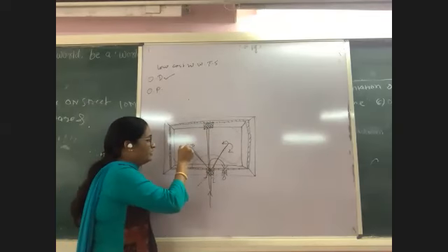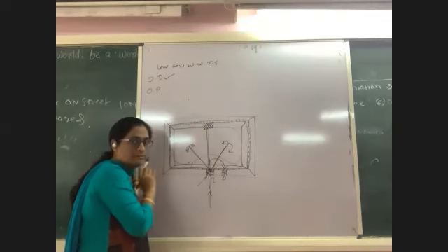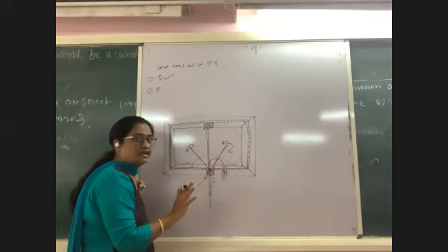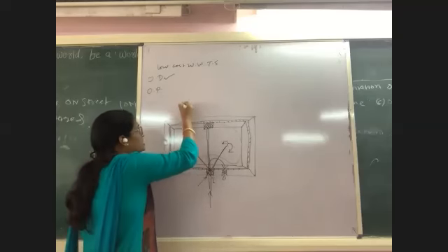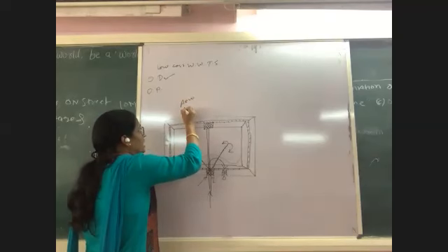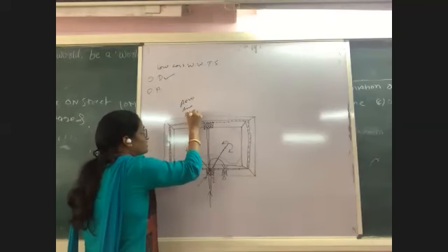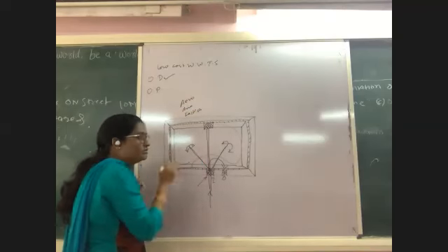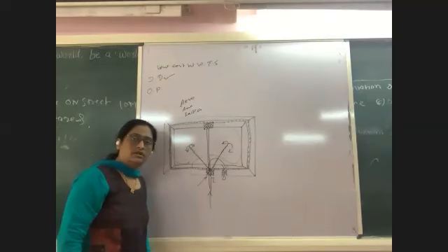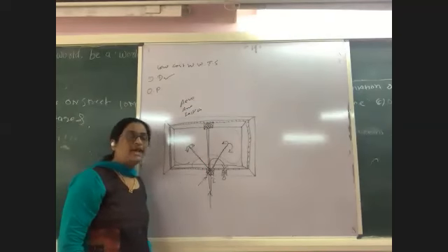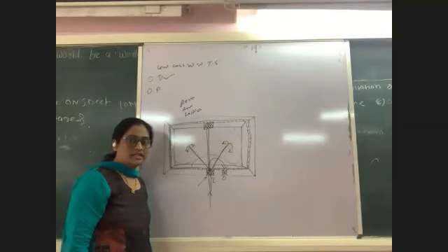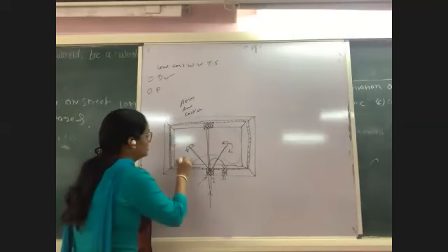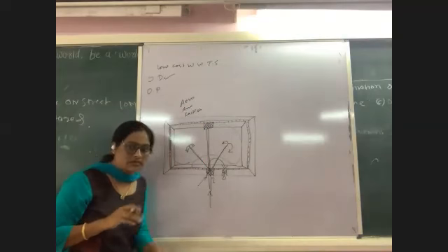And you are allowing the sewage to enter at the center with the help of a pipe. So it is just an open tank. You are continuously depositing the sewage, and 3 different actions can be performed: aerobic action, anaerobic action, and facultative action. Either of these actions will be selected as per the depth of the oxidation pond provided, and it will perform the decomposition of organic waste in the designed tank. So this is nothing but the oxidation pond that we have discussed. We have discussed advantages and disadvantages.